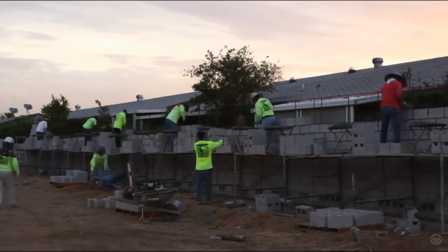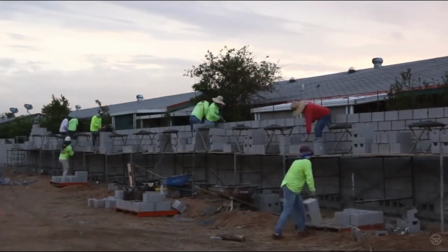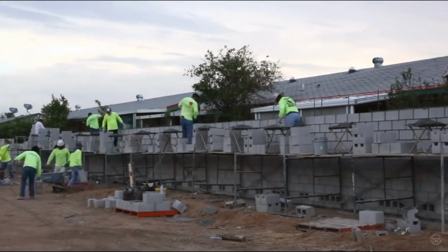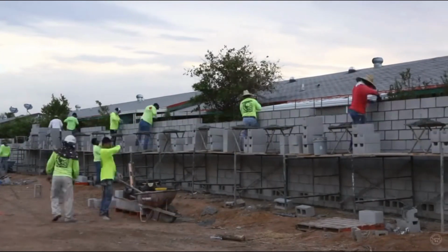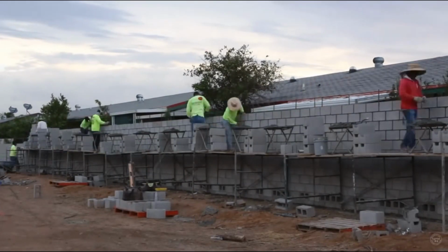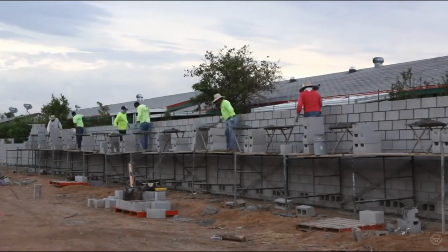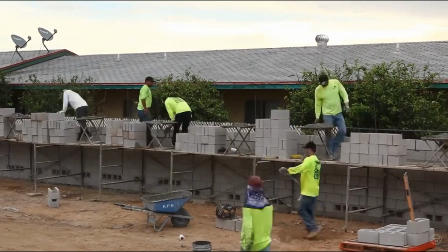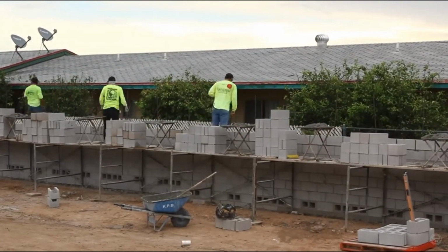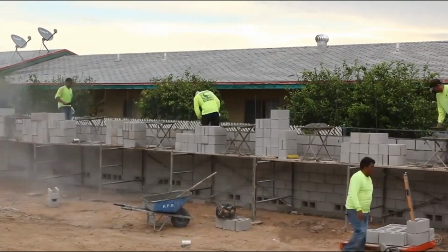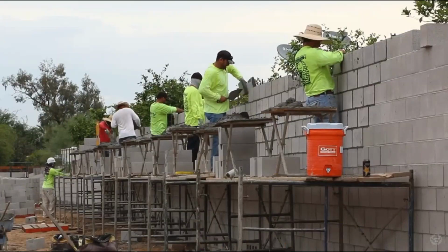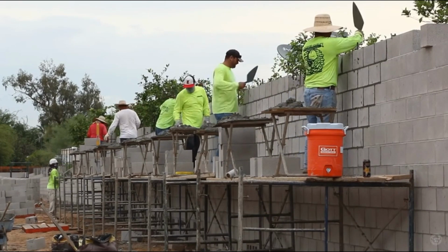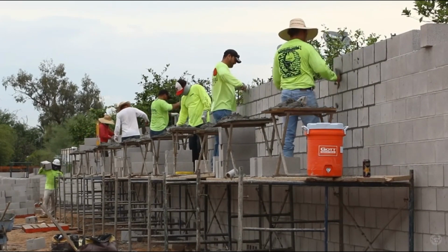So in masonry, what you're looking at here are block masons, and they're putting in a CMU wall. That's a concrete masonry unit. It used to be called cinder block because of the material that was used as the aggregate. They are more uniform now, more testable, more structurally predictable, and they're called concrete masonry units. Unlike some of the other masonry crafts like stone, if you're laying up a stone fireplace or a stone column, you have the variability of Mother Nature's sizes and shapes and textures and colors.